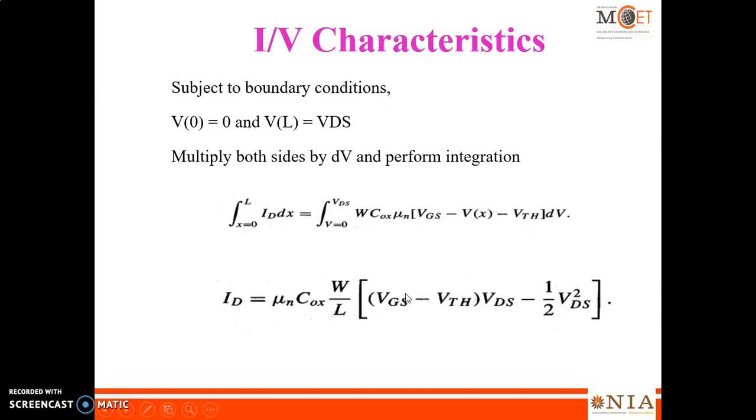Okay, now the next step is to find this drain current for different values of gate to source voltage. Why am I doing this? I should find the maximum value of drain current, which occurs for a particular VGS. So to identify the maximum drain current and the corresponding value of VGS, I am going to substitute different values for this VGS, and then calculate my drain current.